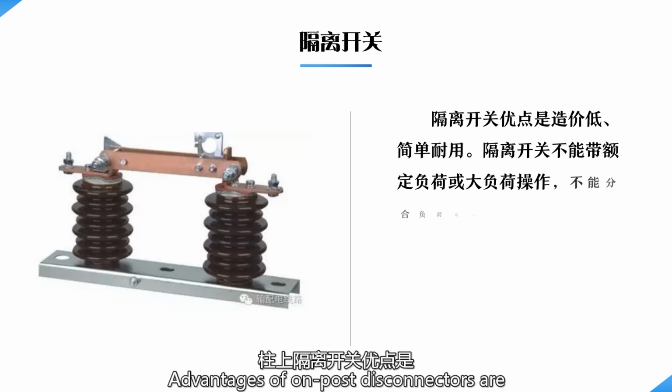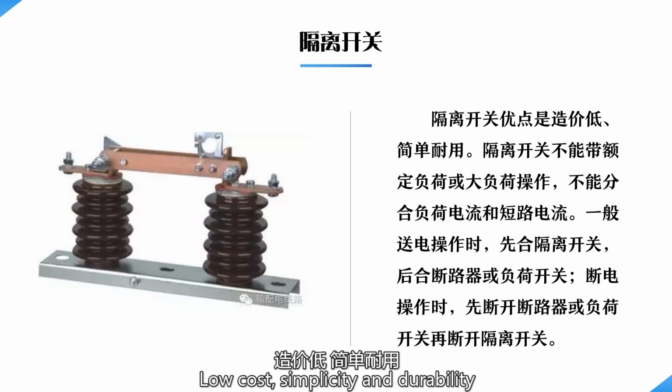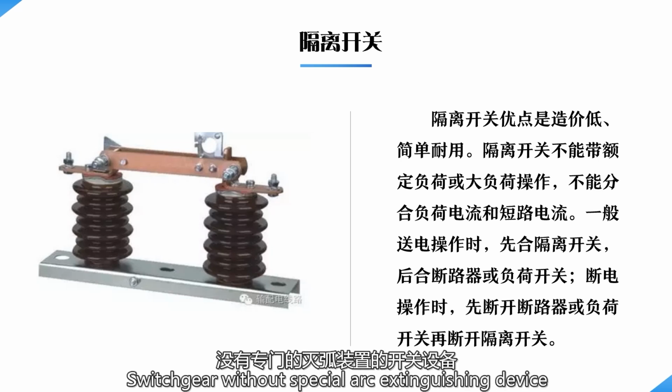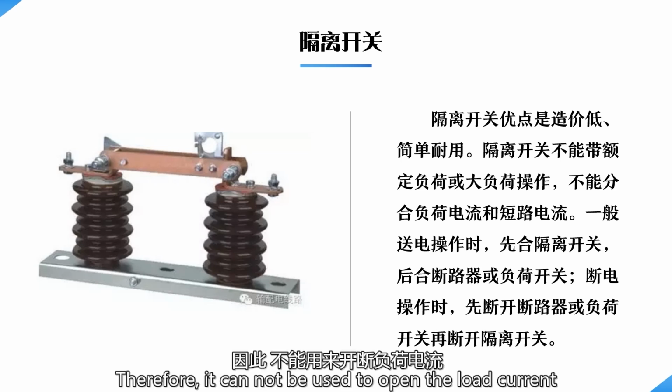Advantages of on-post disconnectors are low cost, simplicity, and durability. Disconnectors are a type of switch gear without a special arc extinguishing device. Arc extinguishing capacity is very weak.